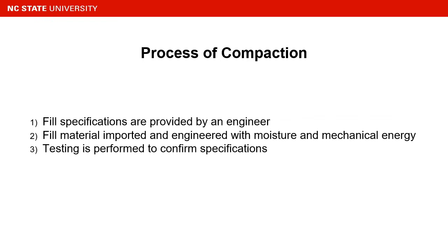The main process of compaction on site is as follows. First, fill specifications are provided by an engineer. Then, fill material is imported and engineered with moisture and mechanical energy. Lastly, testing is performed to confirm specifications are satisfied.